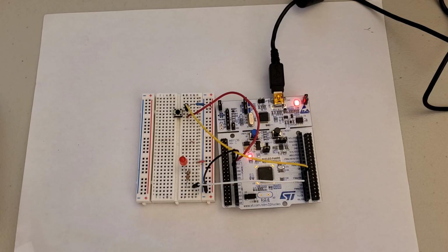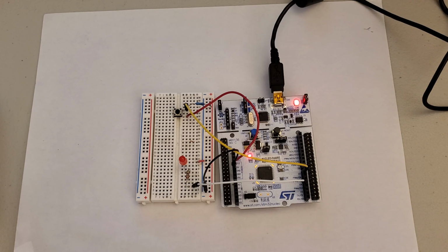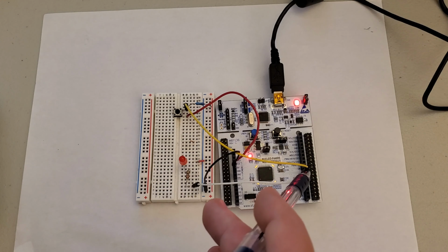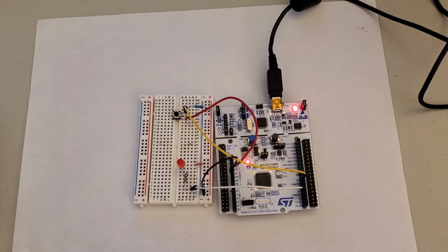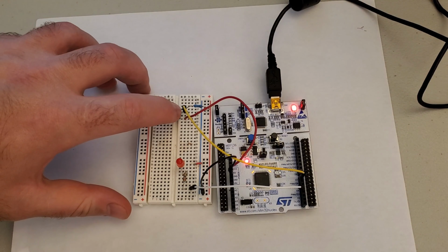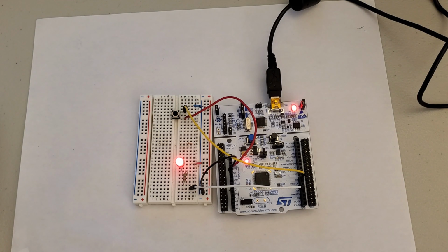This switching is achieved by assigning the interrupt to the pin attached to the button. We actually attached the interrupt to this pin over here. If the interrupt pin detects a rising edge that is created by pressing the button, then the current execution of the code will stop and another function will be called. This function is called the interrupt handler or interrupt service routine. The interrupt service routine is also abbreviated as ISR.